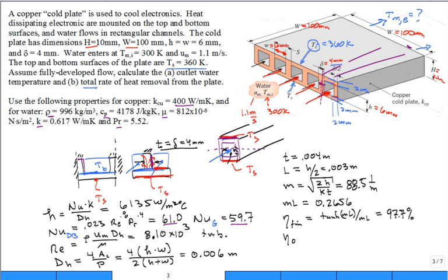But the equation covered, I think, in Chapter 3 for that is that it's equal to 1 minus the area of the fin divided by the area total. The total area is the fin plus the exposed base times 1 minus the efficiency of one fin. All right, so what is this? Area of the fin divided by the area total.